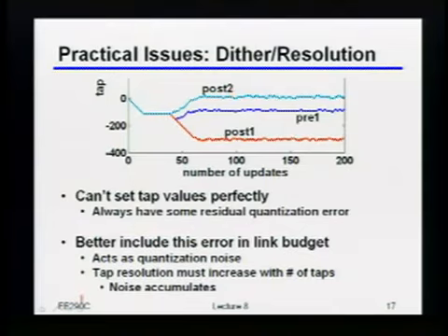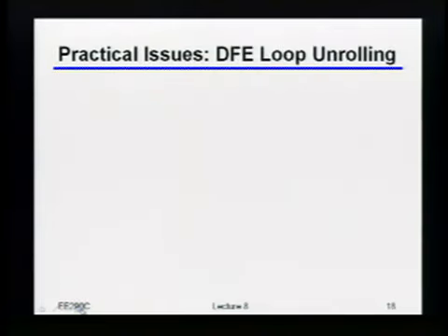Okay, so unless there are more questions on that, the last thing I want to briefly mention is, remember we talked about how once you push things to high enough speeds, you end up trying to do these loop unrolling types of tricks where you push that critical path in the first DFE tap into the digital domain, where maybe you have less penalty from the analog settling and things like that. So just as a reminder, I'll draw one of these things just so that everybody remembers.